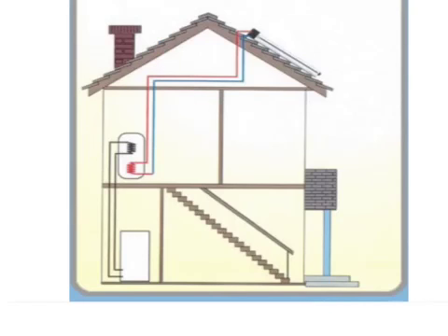So, a typical central heating system. A sensor up here might record the temperature outside. So, say the temperature reaches 2 degrees. All of that data is passed along here. Signal sent to the processor, and the ADC converts it from analog to digital. The computer then instructs the central heating system to turn on so that it warms the house. Likewise, an internal sensor will measure and send back data about the temperature inside, and when it reaches a certain level, say 20 degrees, the heating will be turned off, and this cycle will run continuously.